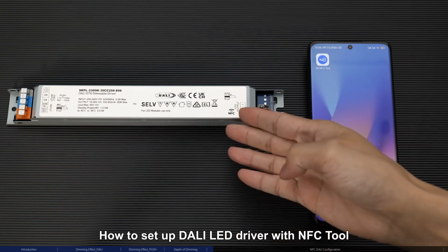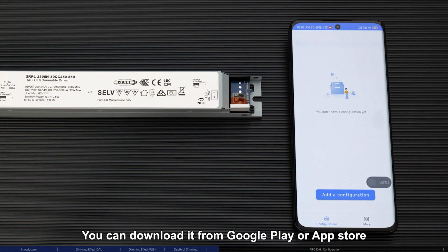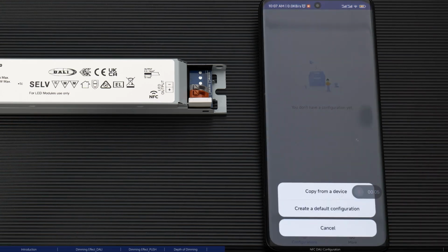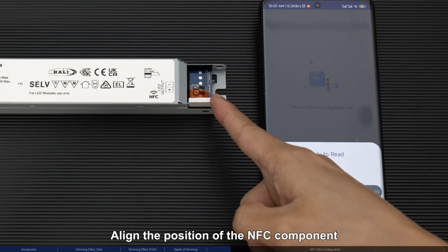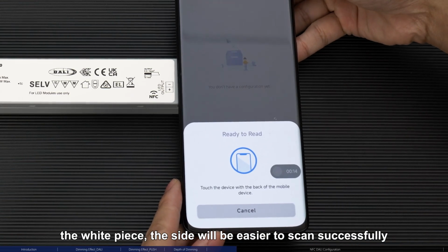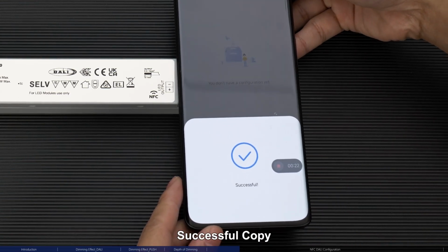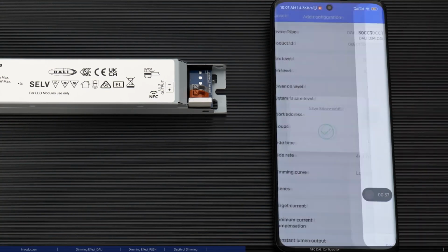How to set up a DALI LED driver with the NFC tool. Enter the SR NFC tool. You can download it from Google Play or the App Store. Add a configuration. Copy from a device. Align the position of the NFC component. The NFC element is here, the white piece. The side will be easier to scan successfully. Successful copy. Save. Type a name and save the configuration.